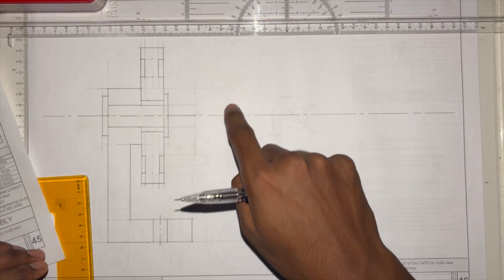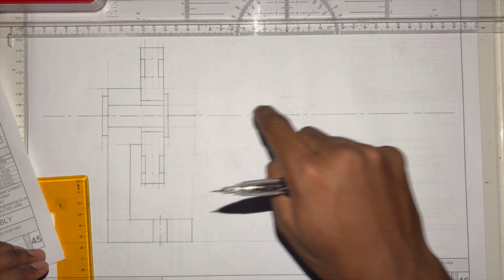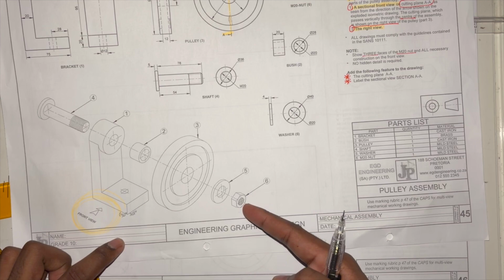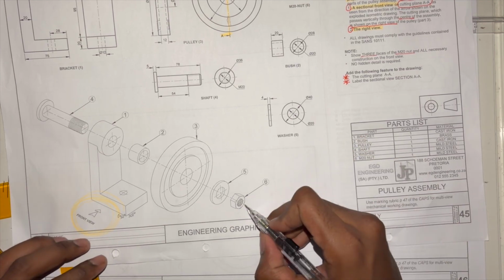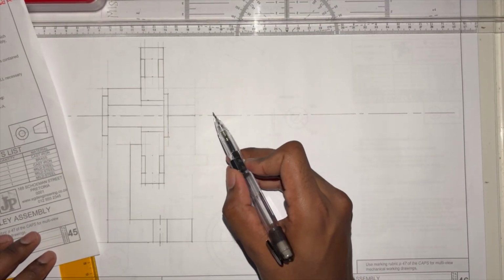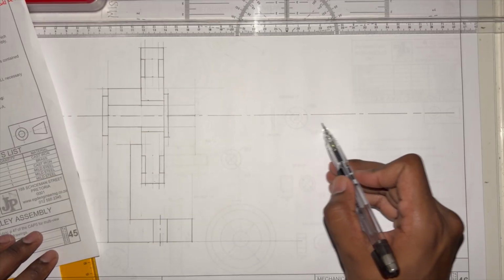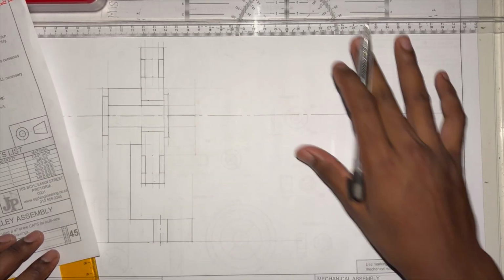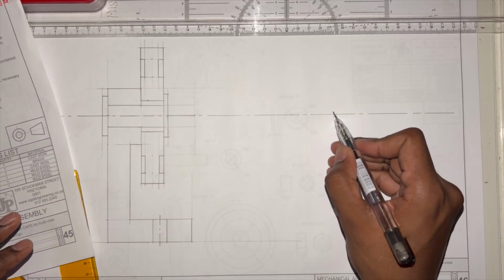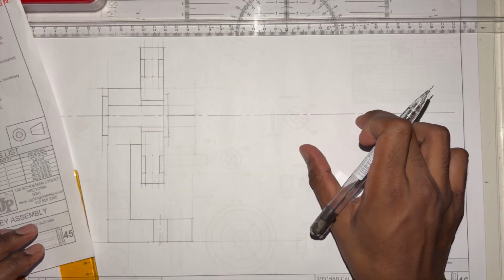Now, instead of drawing an auxiliary view here and then drawing a right view again here, understand something. When I'm looking at this from the right, the first thing I see is the nut. Specifically, what part of the nut? I'm looking at the auxiliary view of the nut. So my advice is don't draw the auxiliary twice. Draw it on the right view. Even if you're not drawing the right view, we're still busy with the front. We haven't hatched. Draw it on the right view. Bring it across. Finish this. Go back to that.